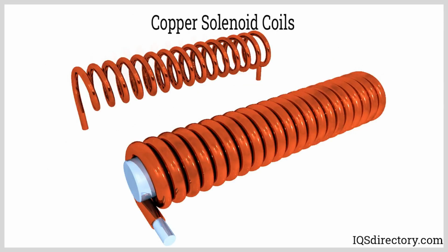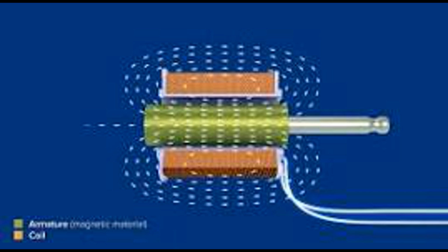3. Holding solenoids. Description: these solenoids are designed to hold or maintain a specific position or load when energized. Operation: unlike other solenoids, which are designed for quick movements, holding solenoids use the magnetic field to keep the core in place for extended periods. Applications: used where long-term activation is needed without continuous motion, such as magnetic clamps or holders,